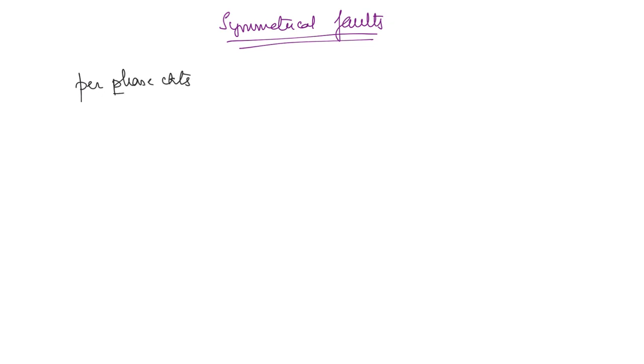Now we will first start our discussion with symmetrical faults. For symmetrical faults, the analysis is comparatively easy because all the phases are balanced. So what we will take is the per phase equivalent circuits. Per phase circuits we can take and we can analyze.